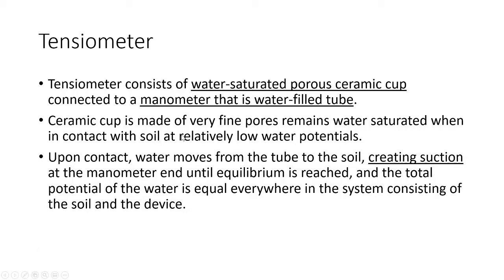So it means it is fully saturated, so there's almost no pressure in it. Upon contact, water moves from the tube to the soil. So it means the soil is actually pulling the water out from the ceramic cup, creating suction at the manometer end until equilibrium is reached.